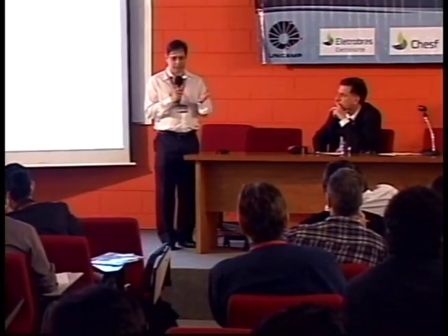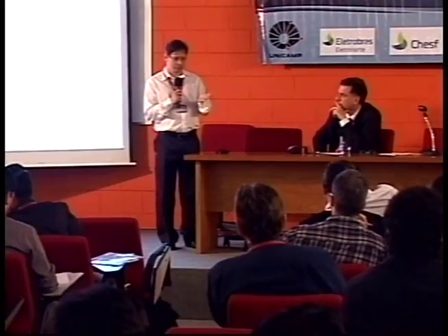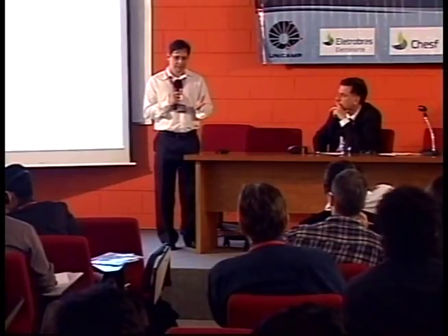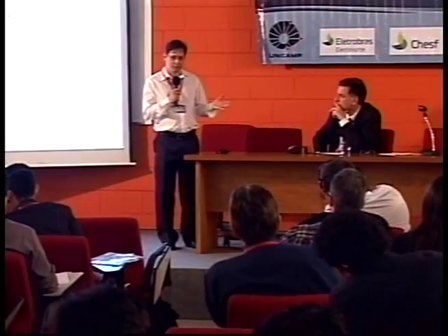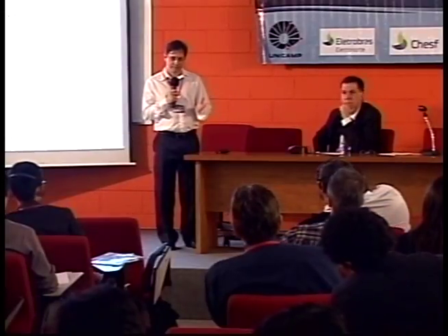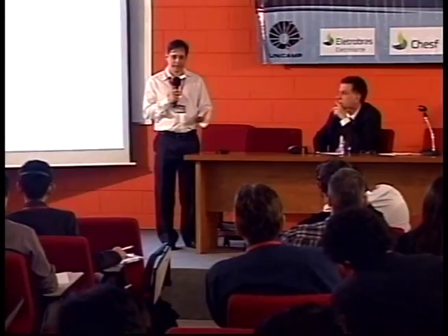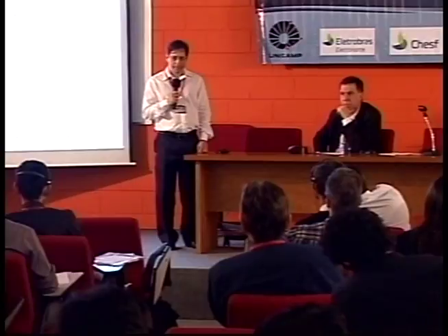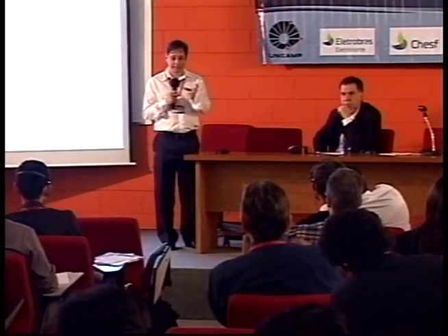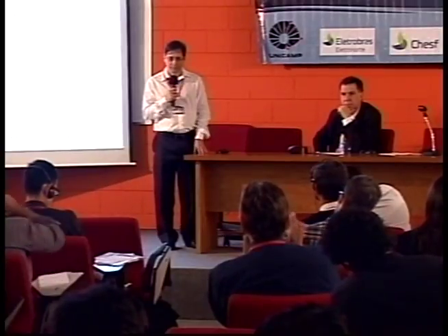ATP uses the line represented by distributed parameters, and in PSCAD we use the representation that takes into consideration the variation of the parameters with the frequency. So this also influences the results, the model of the line.